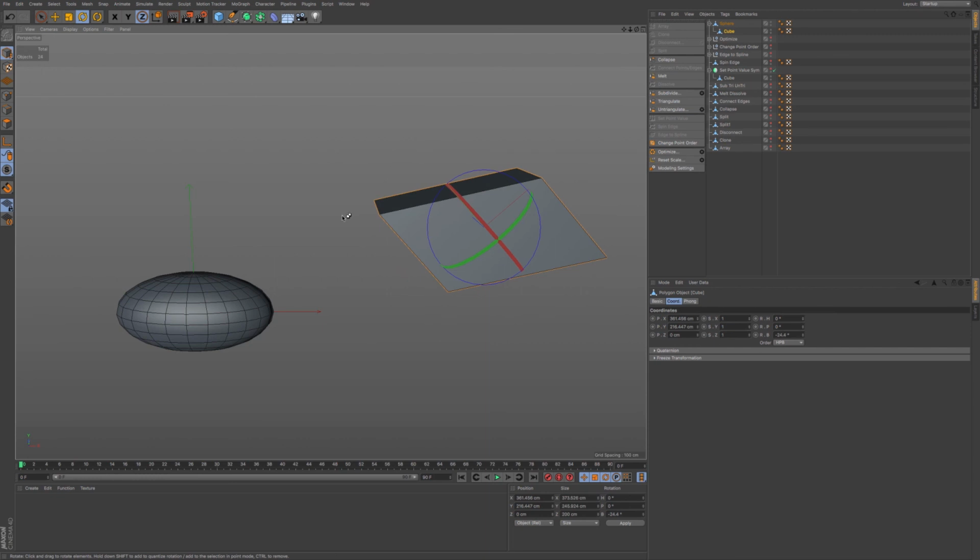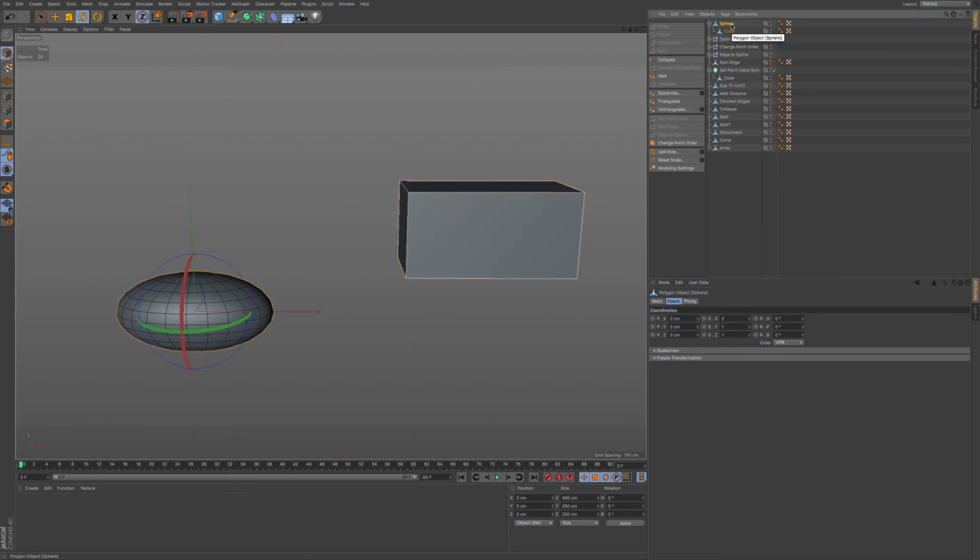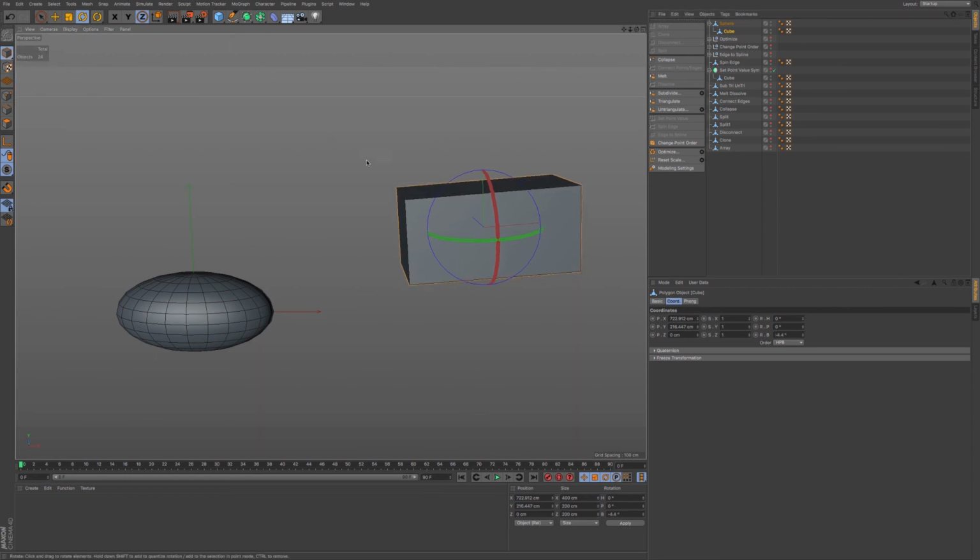So in order to fix that, you would undo, you would select your sphere, where you can see you have the scale set to 2, go to reset scale, click on the gear, make sure you have compensate points and reset child objects checked. Select OK. Now, when you want to make a change to your model, you'll go to model mode and rotate, and you can see now you don't have that distortion.